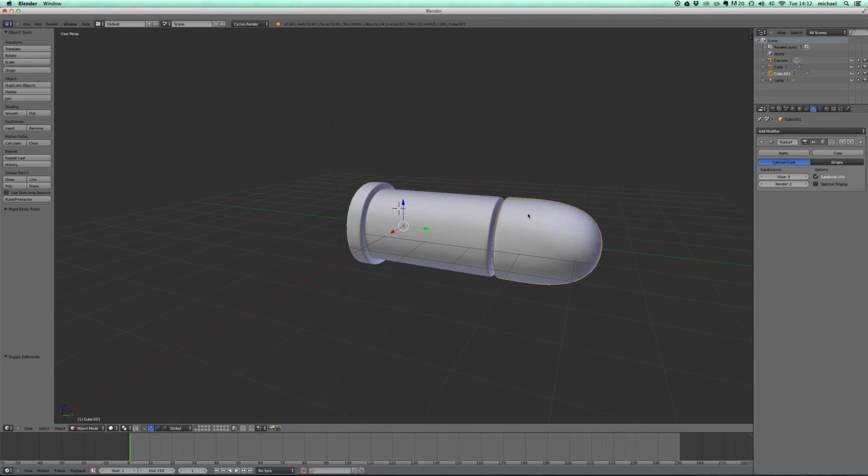So what I'm going to do first is change this one to a different color. Up here, you've got lots of different options for every object. So selecting your object, go to here, and this is the materials. At the moment it's got a default material, which is just a grey material that is irrelevant. It doesn't mean anything, so I'm going to get rid of that. It slightly changes color because it goes back to a base color. I'm going to click on the other object and delete that material as well. So now none of these objects have got a material.